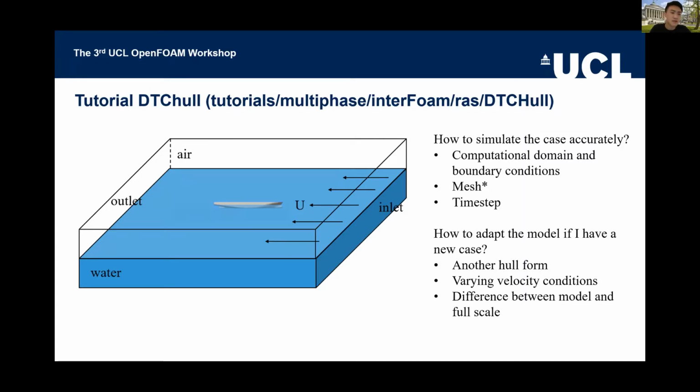This will be based on a tutorial case, the DTC Hull. You can find it in your OpenFOAM tutorials: multiphase, interFoam, RAS, DTCHull. First of all, I will need you to have a tour of this tutorial case together, because it's well tuned by OpenFOAM, but I will need you to read some directories and tell you how this was done.